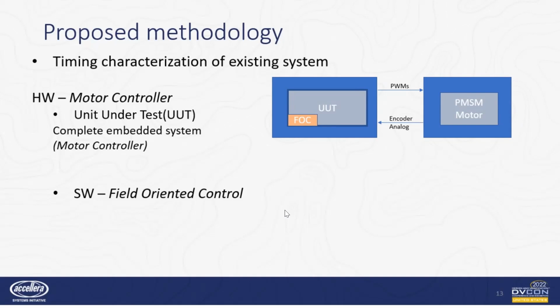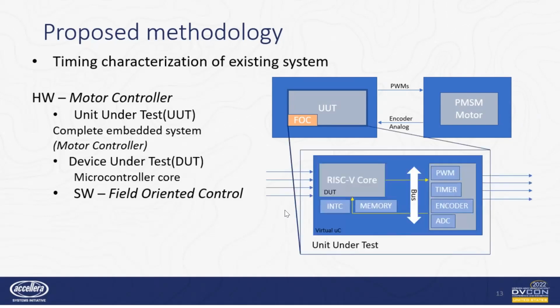This will be the reference metric for the new system, obtained by response time measurements of the unit under test in different test case scenarios and regression runs. We are particularly interested in measuring the response time from interrupts actions relevant for the system reporting the motor state. With the same structure, the test bench will implicitly exercise and evaluate the RISC-V core